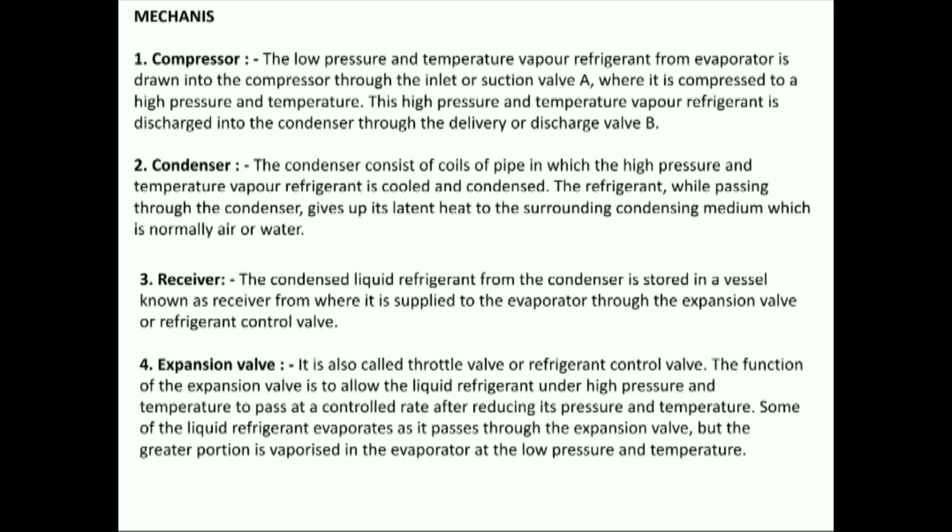4. Expansion valve. It is also called throttle valve or refrigerant control valve. The function of the expansion valve is to allow the liquid refrigerant under high pressure and temperature to pass at a controlled rate after reducing its pressure and temperature. Some of the liquid refrigerant evaporates as it passes through the expansion valve, but the greater portion is vaporized in the evaporator at the low pressure and temperature.